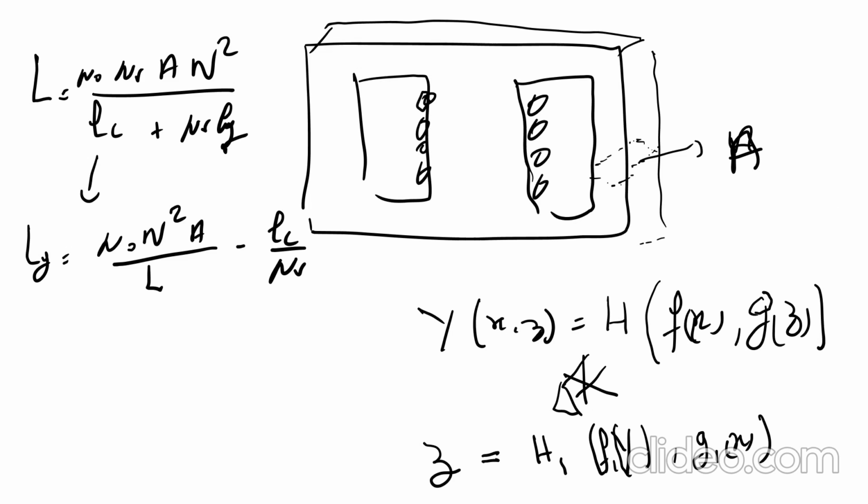To understand why the air gap does not depend on the cross section, there are several ways to prove this. The first approach is by intuition. Consider the following example. Suppose that you have designed your inductor. You have selected your magnetic core that has a specific magnetic length, and you have selected the number of turns and so on. You have also calculated the required air gap. Then you need to change the design because the magnetic flux density increases due to an increase of the current. You are changing the application, or you are changing the excitation voltage.